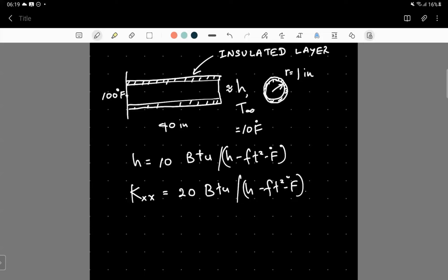There will be convective heat loss only over the right hand end, which is exposed to the free stream. We consider the left hand end to have a known temperature, and of course the perimeter of the rod to be insulated. Then after we develop the finite element model, we can calculate the stiffness matrices for each element, assemble the total stiffness matrix, apply boundary conditions, and calculate the relevant temperatures. Quite simple and straightforward. It is the same procedure which you applied when solving structure related problems.